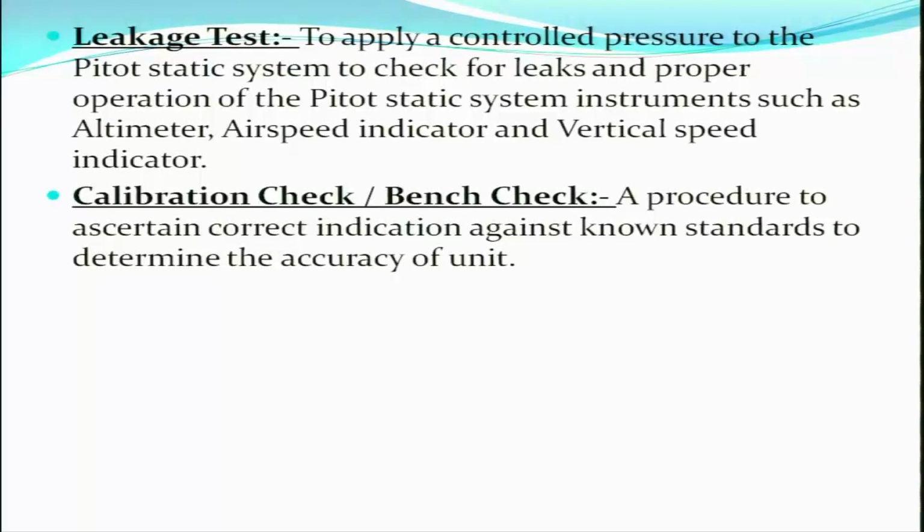So, a controlled pressure is applied to the pitot static system and proper operation of the instruments is checked by seeing whether there is any leak in the instrument line, in the instrument system or not.